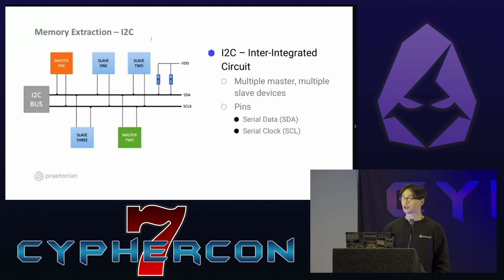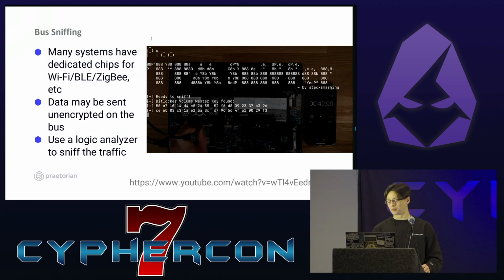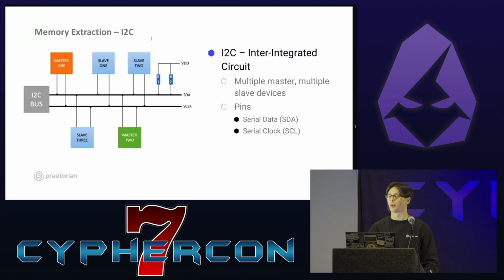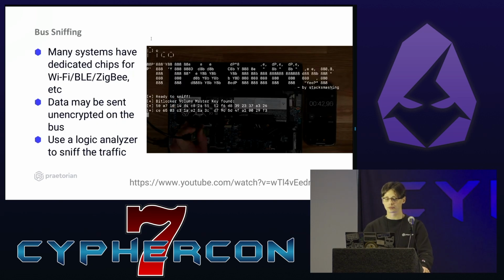Another protocol you're going to see a lot for extracting external memory devices is I2C, or if you meet a real old timer, they might call it IIC. So if you hear any of those, that's what this is referring to. With this, you're just going to have to find those SDA and SCL lines. And again, the same tools like the Bus Pirate, those will be very helpful for interfacing with that protocol.